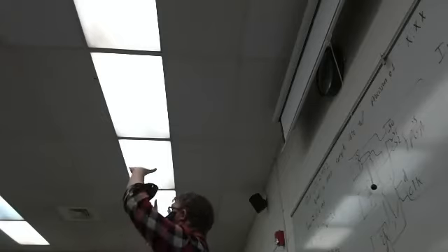Okay, so if it drops and you're low, then it's the rising edge that triggers it. Yeah, if you drop while it's high, rising edge. If you drop while it's low, falling edge. Okay, so that way it gives it one full clock cycle. Yeah, so it can be either edge triggered, which is actually really interesting.